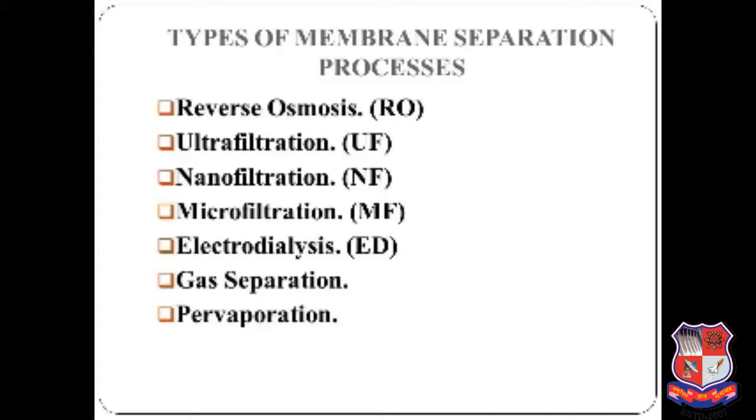The widely used membrane processes include microfiltration, ultrafiltration, nanofiltration, reverse osmosis, electrodialysis, dialysis, gas separation, vapor permeation, pervaporation, membrane distillation, and membrane contactors. All processes except for pervaporation involve no phase change. All processes except electrodialysis are pressure driven.